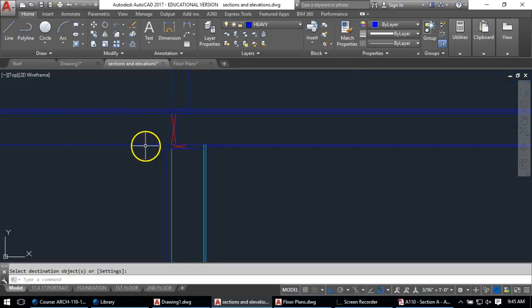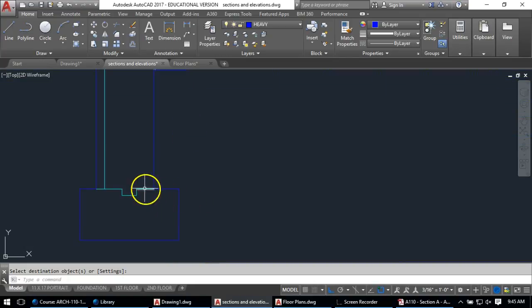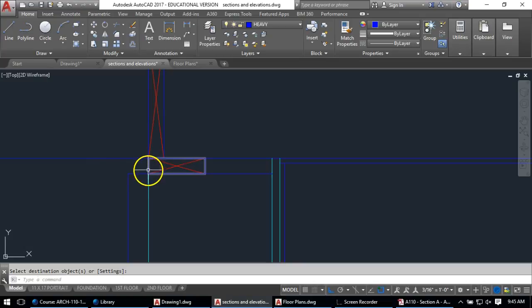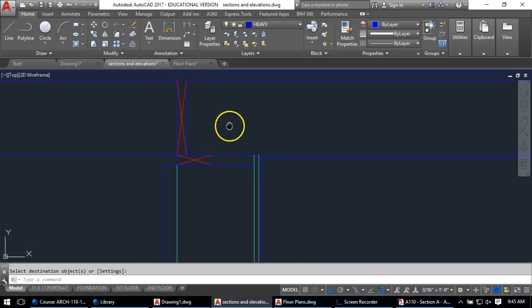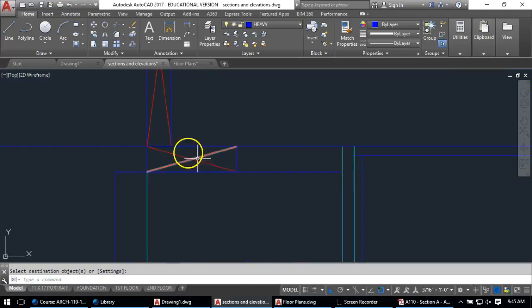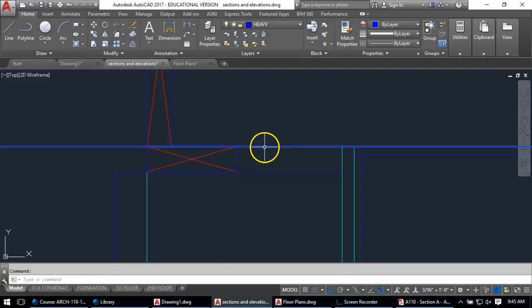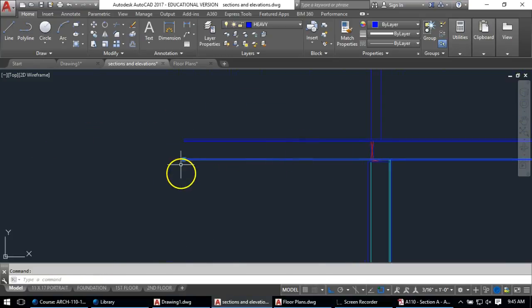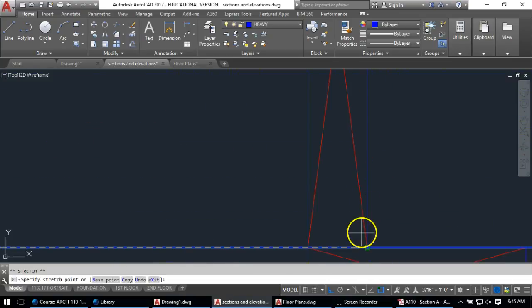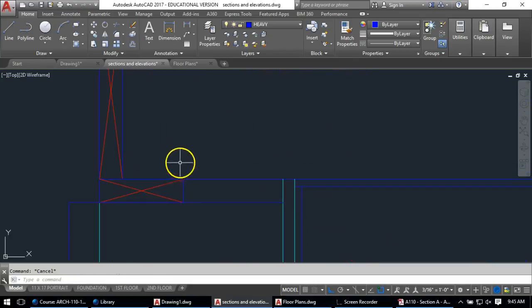Right? There are different rules; there are no exact rules. I could have argued that since this was part of the same line, it'd be clearly easy to read, and I could have left that as cut. And since I made these polylines, instead of saying this is an exterior face and this one partially is, I'm just going to leave my 2x4s all as thick lines. But I do, of course, have the X's on a lighter line weight. Now this joist is going to be stopped here, so I can pull this back to this location.